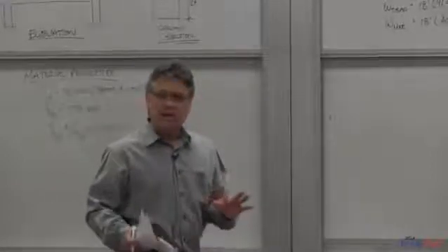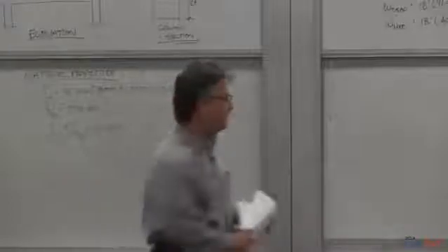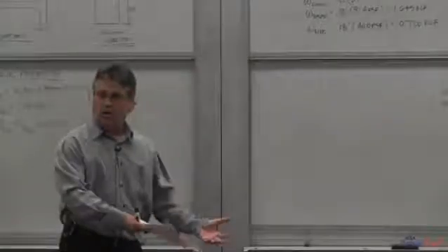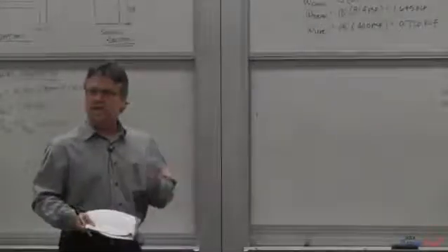So we haven't gotten to what I'm telling you to do yet, but this is how I want you to show me. And I will get lines of people who come in and say, I'm only balancing 69.3% of the dead load in your example. You said 70, or whatever I've asked you to do. The theory is this is an approximation. You're just trying to come up with the nice round number of tendons that you need. There's going to be 9, or 10, or 11, or 12. This is the estimate to get close to that number.